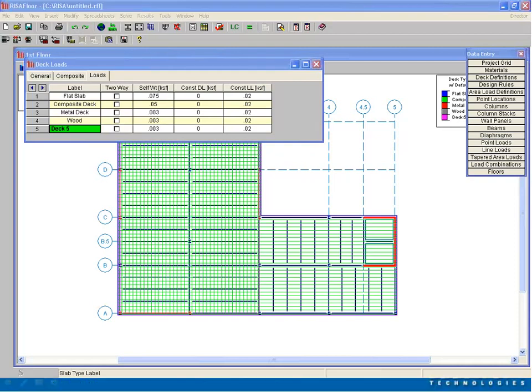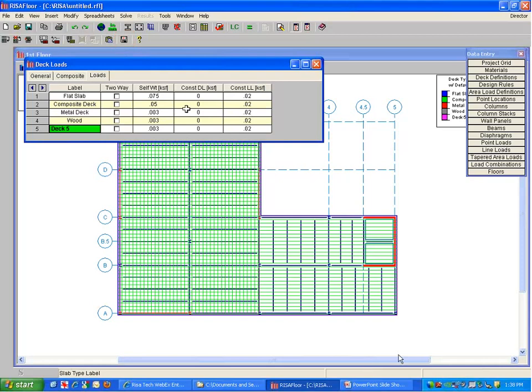You can also save some of these decks. So if you're working with decks all the time, you can come up to the default button at the top here, and you can choose default. So as soon as you set up your own parameters the way you want them to be, you can save that to your model and click the default button. So then when you start a new model, you'll have your defaults all set for you. So you won't have to recreate those every time you go in there. So that's real helpful too.